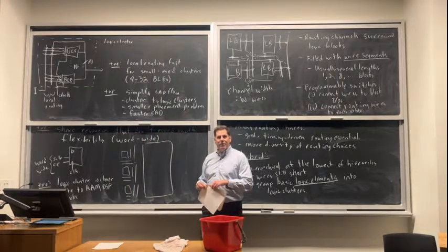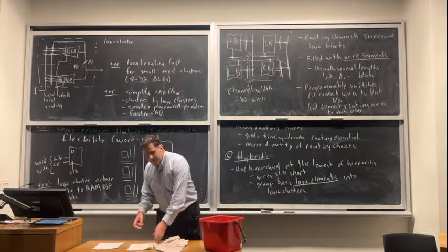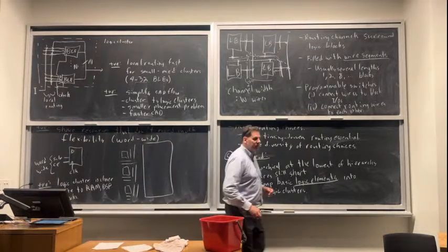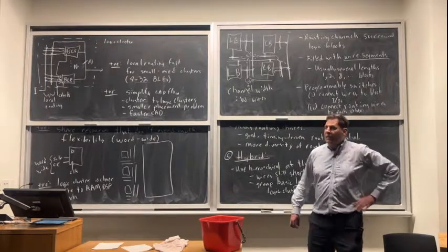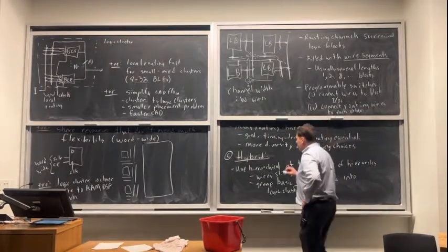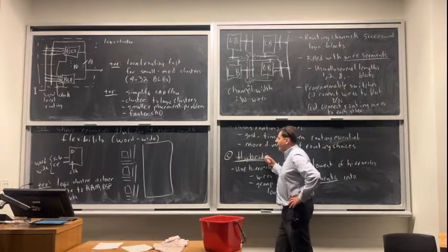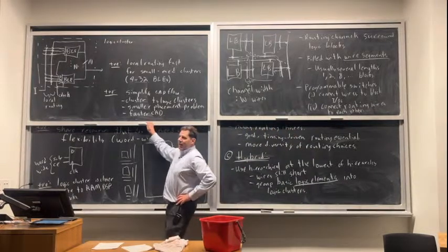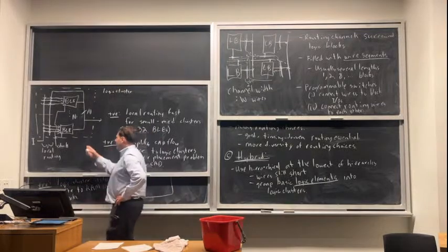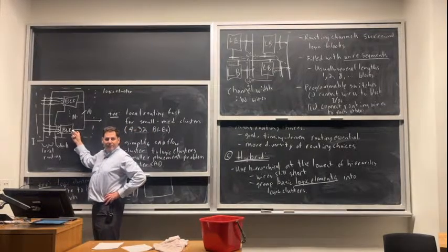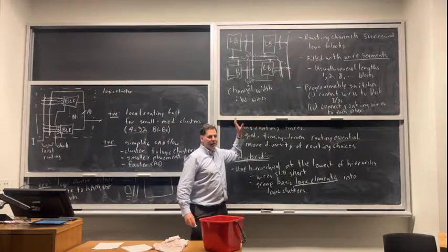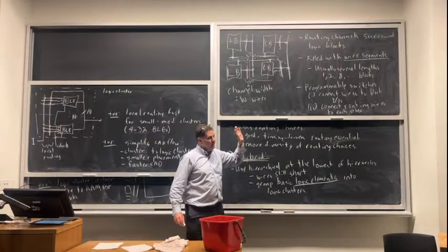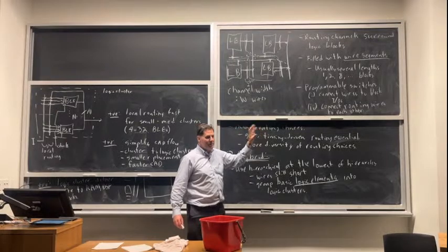Okay, so any questions on any of this? Yeah? Like in industry, is there a trend that they're moving to hybrid or to stick to hybrid? Hybrid is now dominant. So Altera, basically, because they had hierarchical FPGAs, they used logic blocks like this for quite a while. And Xilinx used little logic blocks, like lookup tables, maybe just one lookup table and then maybe two, but not with any local routing.